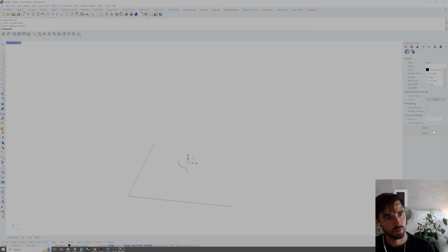If we go to properties and details, we can actually see the object description of that point. The point has been added, and it is precisely at 32.2751, comma, so that's the x coordinate there, comma 45.2025, and then as I mentioned, 0 on the z-axis. So if I go ahead and hit close and then delete that point,